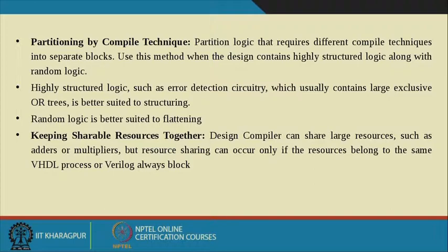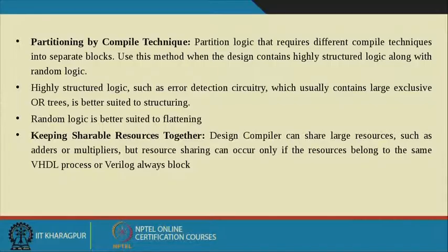Another thing we can do in design compiler is partition by compile technique. If I am going to design a complex block with several other complex sub-blocks, then I have to perform this partitioning. For a simpler block it is not that necessary. You can do it, but it is not at all necessary. It is necessary whenever we are designing a bigger or complex circuit.